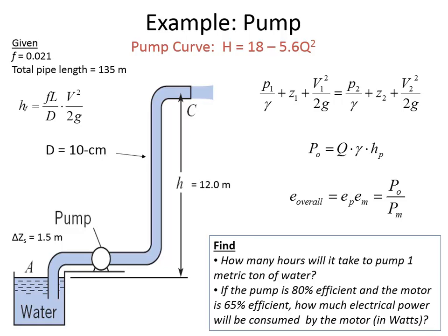Now, there's two components of head losses: the friction losses and the local losses. So in this instance, we have an inlet loss of 1.0, so it'll be plus 1 times the velocity head, Q squared divided by 2gA squared. And this is local loss.